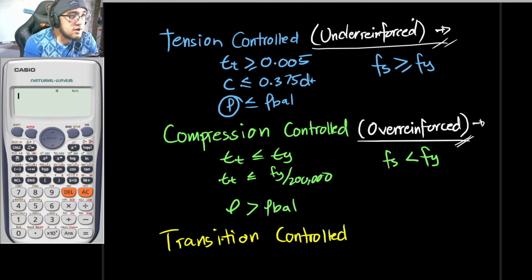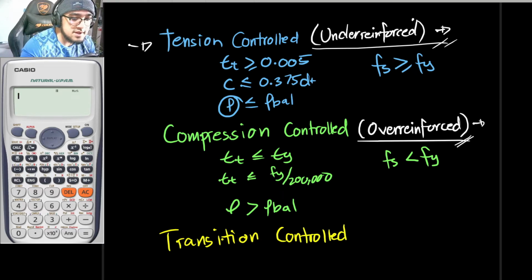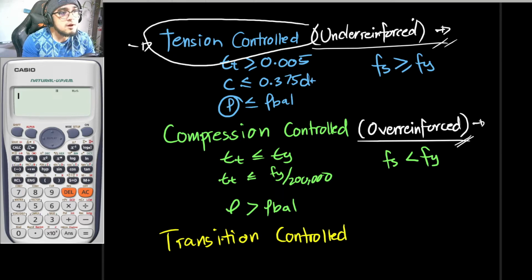Once again, for your tension controlled, you would still have your warnings. There will be cracks first and it will slowly fail. And as for your compression controlled, without warning, babagsak at babagsak na lang yan. I will be explaining to you via computations very soon why compression controlled is not advisable and tension controlled is the much better design parameter.